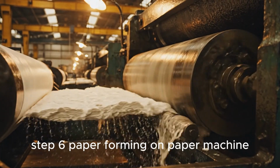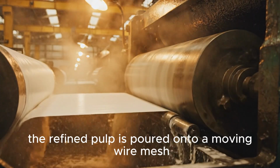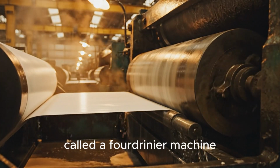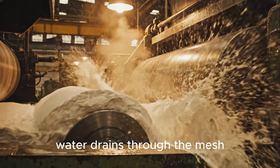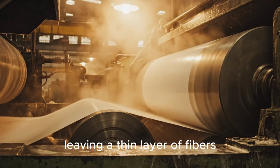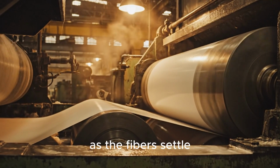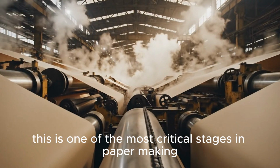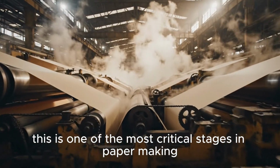Step 6. Paper forming on the paper machine. The refined pulp is poured onto a moving wire mesh in the paper machine. Water drains through the mesh, leaving a thin layer of fibers. As the fibers settle, they bond naturally to form a continuous paper sheet. This is one of the most critical stages in paper manufacturing.